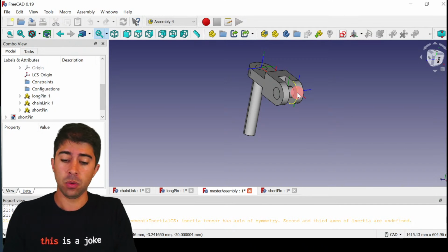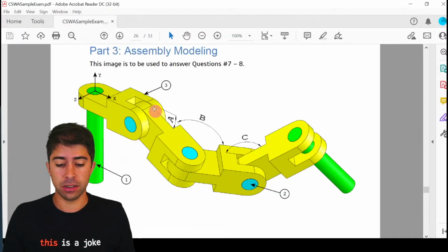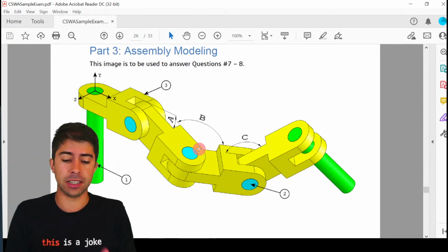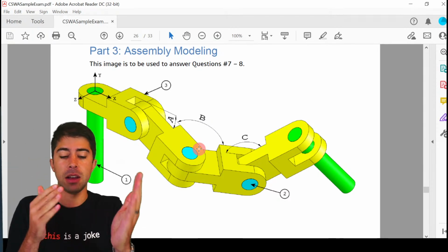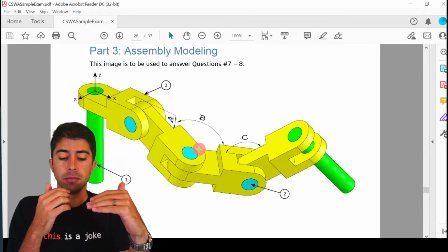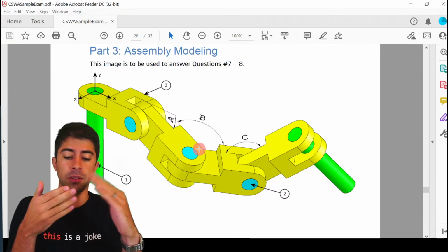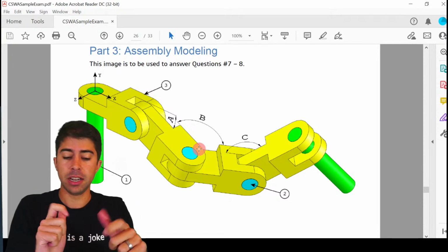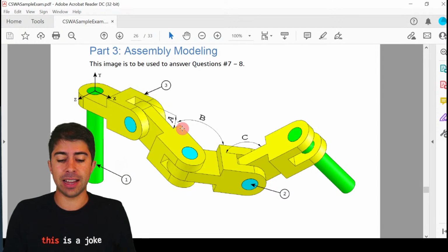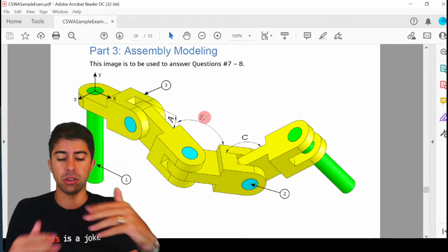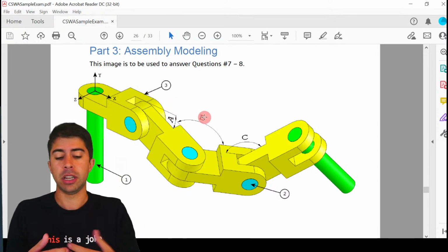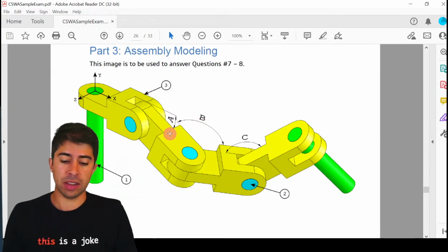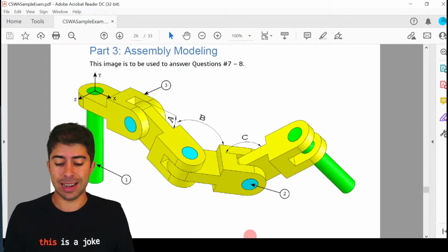So now we need to add our second chain link, and this is where it becomes critical that we had the center point, because now as we want to rotate it, we need to make sure that we are correct. With all the previous parts, I rotated them until they were correct. Now that rotation we can change, and that is where we're going to use this A value. I've just done it with 90 degree intervals, but after you press OK, you can go back and change it to whatever value, and this is where we're going to input the A value.